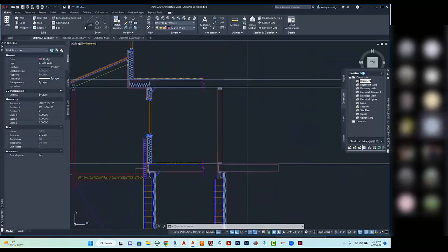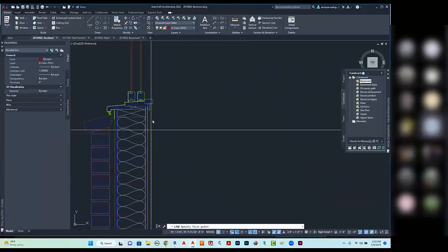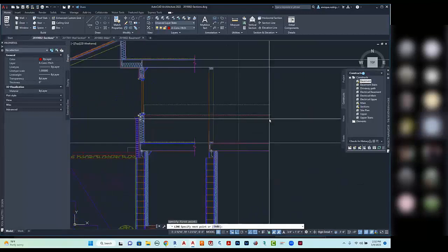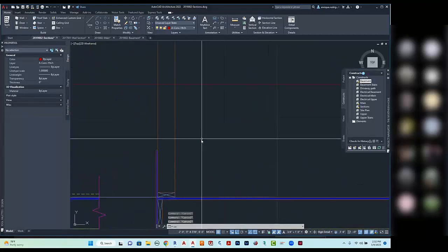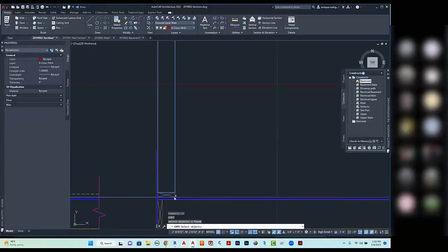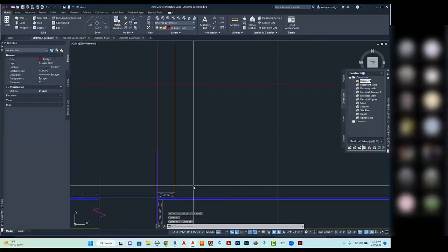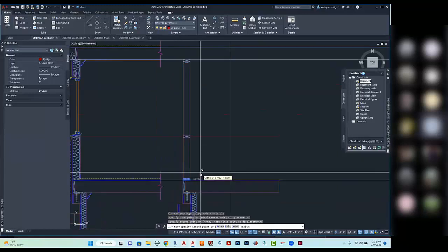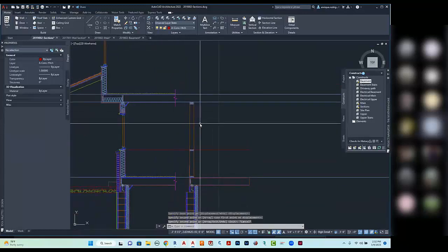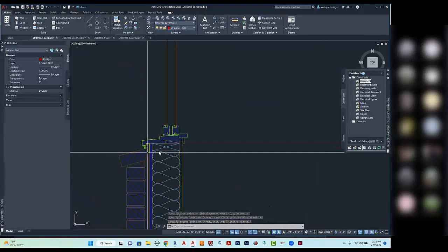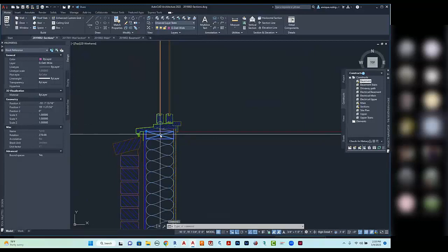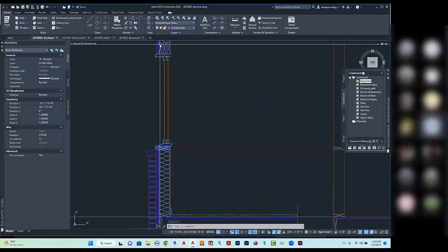So I'm going to go ahead and draw a temporary line from the top of the plate at that point. I'm going to go ahead and copy this element, 2x6, and set it up in here. So what I'm doing is I'm framing the opening for the window. Now the sill is fine as a 2x element right in here.